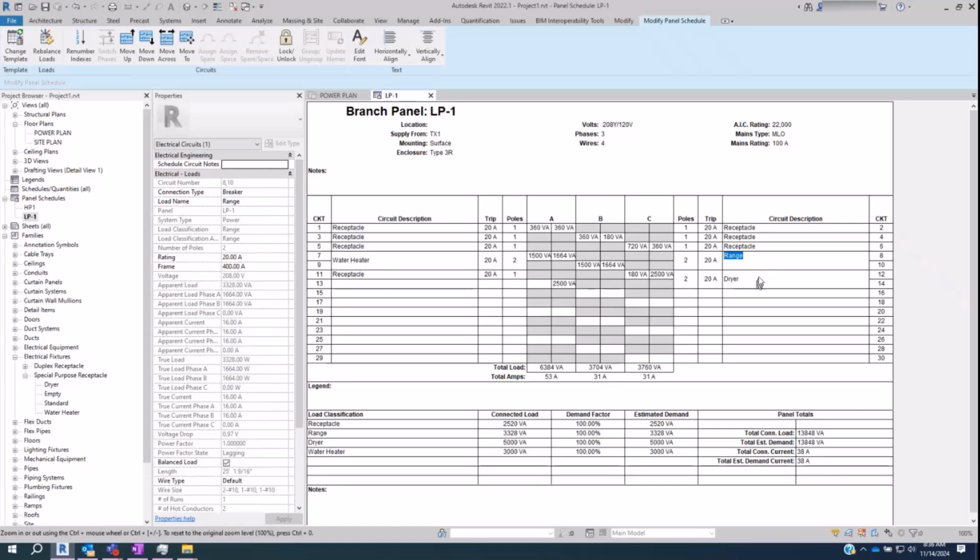Okay, so based on our updated range and our updated dryer loads, what should we actually be putting in for breakers now? That's exactly 30 amps. It's 30.04. So I'm assuming we could round down. So a 30 amp breaker for the dryer. Did the 1.25 rule: 5,000 divided by 208, and then multiplied by 1.25.